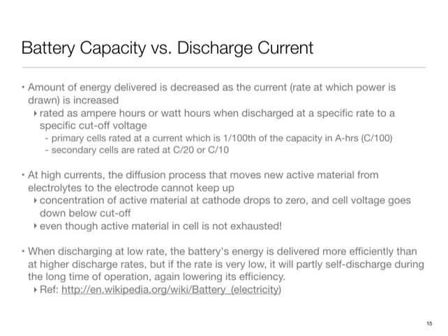The other trade-off that you would see is that now think about, so focus on this issue of battery capacity versus discharge current. Am I better off, from an overall work done before the battery dies perspective, running my processor at a lower frequency, lower voltage, but drawing current over a longer time because my processor is slower? So will I be able to do more work before the battery dies? Because remember now I'm drawing current at a lower rate, a lower amount of current, and therefore I will get more out of the battery potentially, right? Because of that discharge current dependence. Or am I better off running the processor more rapidly? And okay, so there is a dependence. How you set your load related to battery matters as well.